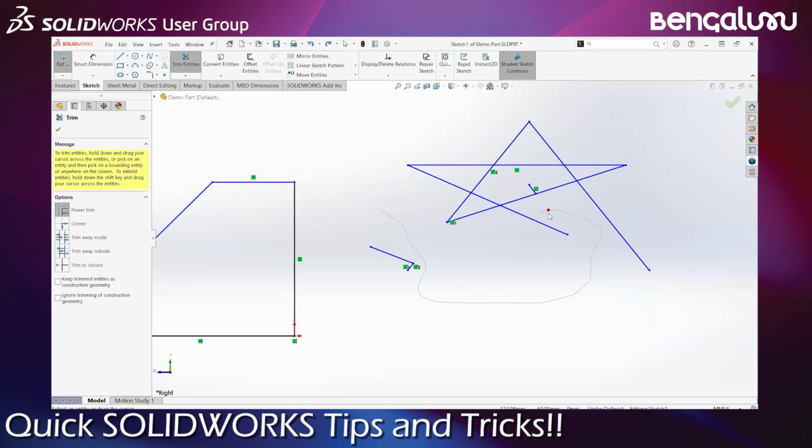You can see this red dot here in the graphics area. So I trim this and it follows me, right? The whole point of that is, without releasing the mouse click, you can simply go back to that. If you take your mouse to that red dot, you see that it actually adds back whatever it has trimmed earlier. See, I move back, I take it back. So that's the whole point of why that has been given in the UI.